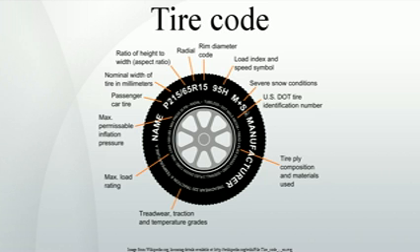Flotation sizes. Some light truck tires follow the light truck numeric or light truck high flotation systems, indicated by the letters LT at the end instead of the beginning of the sequence, as follows. The tire diameter is given for high flotation tires and omitted from numeric tires. 2-digit number, the diameter of the tire in inches. X, separator character. 3 or 4-digit number, the section width, cross-section, of the tire in inches.